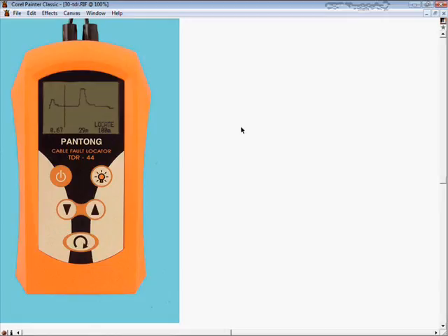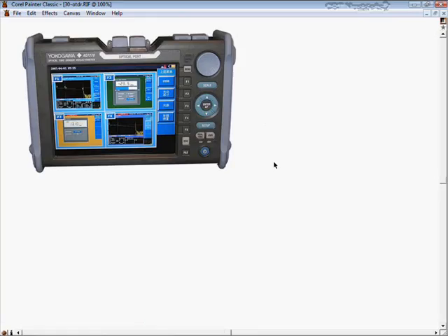But we can also use one for optical fiber. This one won't work for optical, but we have an option for optical. Let's take a look at that one. This is an OTDR, very popular, Yokogawa. This is an optical TDR, or optoelectronics, that characterizes optical fibers, injecting a series of optical pulses into the fiber. It can also extract from the same end of the fiber light, and can be used to estimate the fiber's length and overall attenuation. You can also locate splice and connector losses as well. You can locate faults such as breaks and measure optical return loss. OTDR.